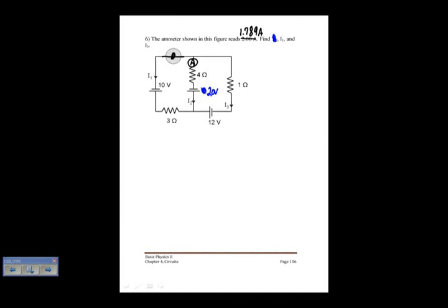1.789 amps. And then I also say that the current I2 is in the proper direction, because as you know, sometimes you can choose the direction incorrectly. But in this case, if you find I2, it's going to be positive 1.789. That means that I2 has that magnitude, and it's also flowing downward. Okay, so now I want to find I1 and I3.